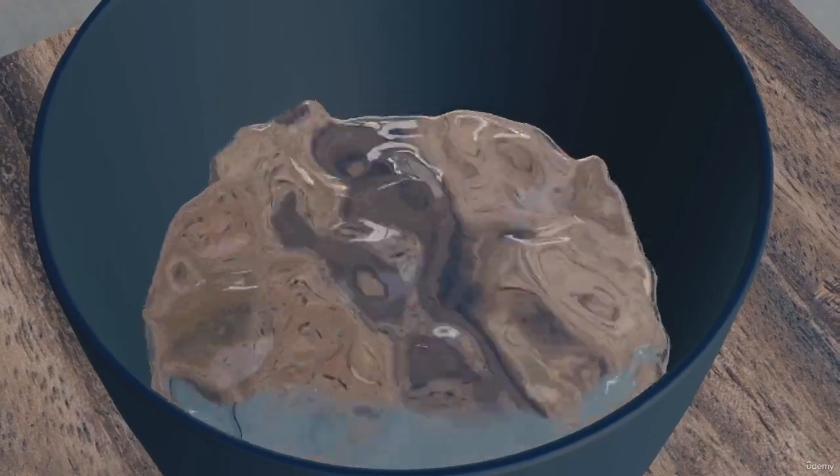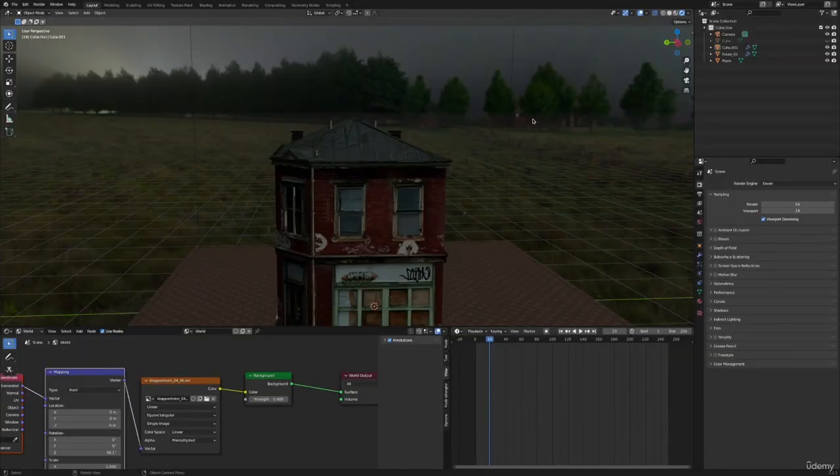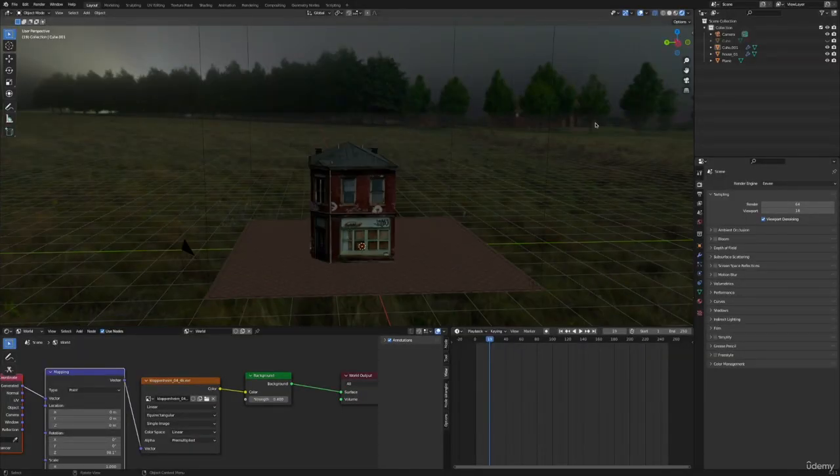Maybe you remember that I said that the domain then became this mesh. In other words, the cube of our domain becomes the geometry, this mesh. And now we can also shade this mesh, just like we did with a liquid simulation. It's very similar. A lot of the things behave the same, only now there's a difference, and the difference is that our smoke simulation has no surface. We only have a volume.